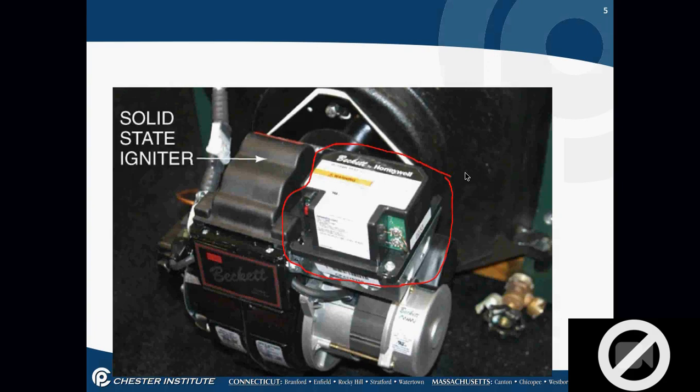No idea. That's my primary control. Okay, we're going to spend a lot of time on this, but this is my entire safety, my sequencing for the motor, for the igniter, and over here there's probably an oil valve if I'm looking at this correctly. There's a wire that's coming from there. So everything on the sequencing of the oil burner comes from the primary control. Okay? It has everything to do with safety. You can't just run an oil burner by plugging it in and turning it on.